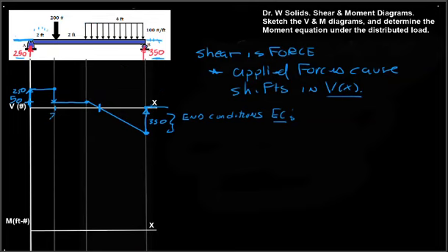If we label this, this is 2 feet, 4 feet. This would be 4.5, and this would be 8 feet along the x. And there we have our shear diagram. And keep in mind that the values for this shear always point towards the axis internally. So if we want to know what direction they were acting. So there we have our shear diagram completed.